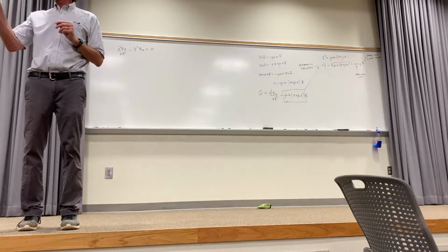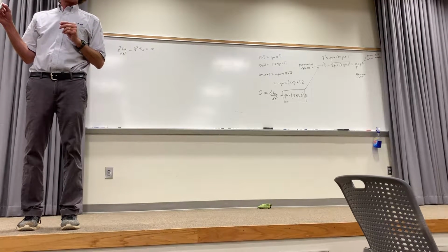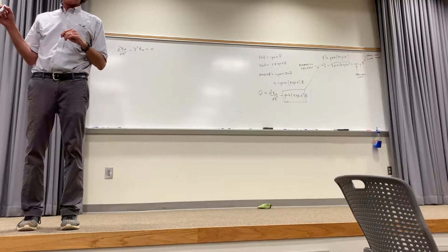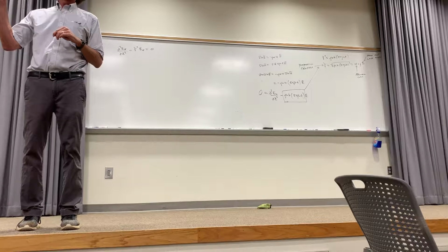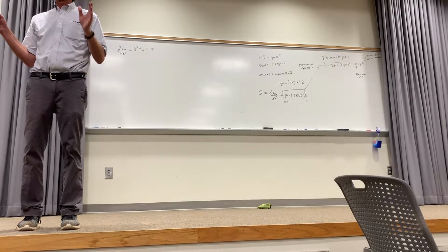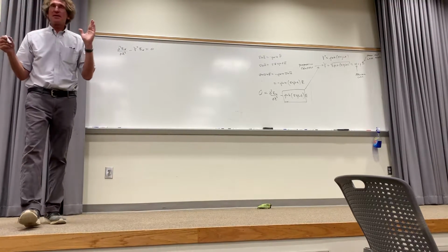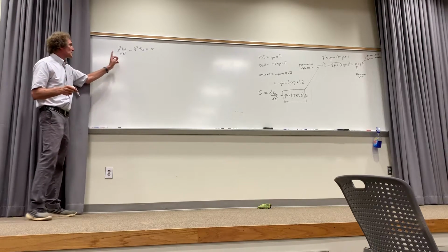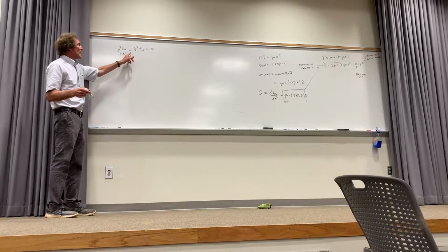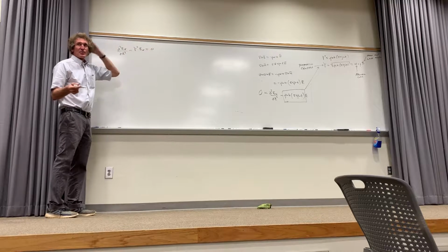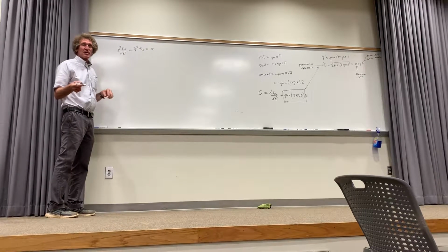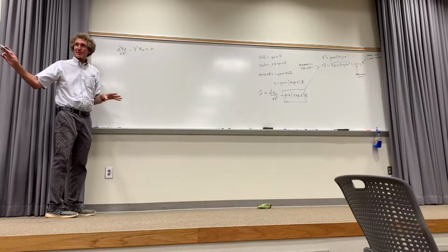And then it's minus s times the value of E in the time domain at t equals 0, and then minus the second derivative of the E field in the time domain at t equals 0. Well, anytime it's steady state, you get rid of those derivatives. This is just going to be s squared minus gamma squared times E Laplace equals 0, and you get two exponentials. I'm not going to go there. I'm going to do it differently.